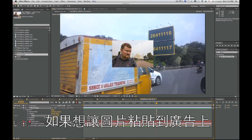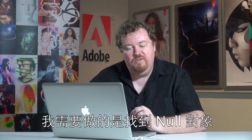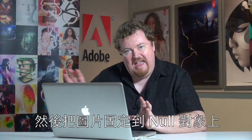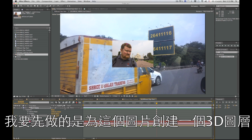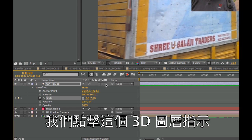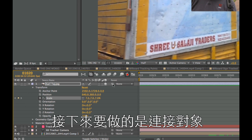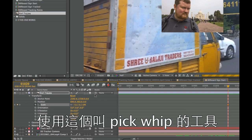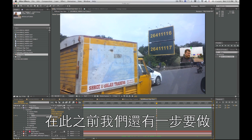Now to make this active and actually get it onto the billboard, I need to get it where the null object is. I want to anchor it to that null object. So the first thing I need to do is make this picture a 3D layer. So we do that by clicking on the little 3D layer indicator. And then I'm going to parent it using this little tool called the pick whip.